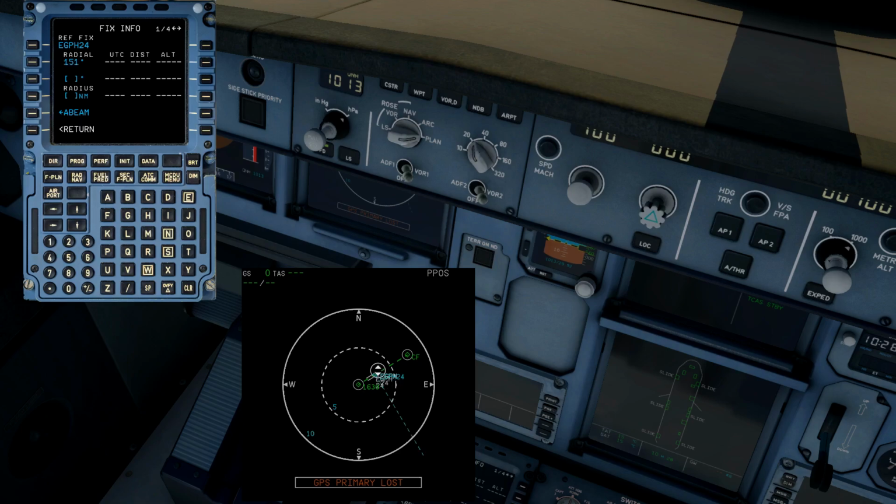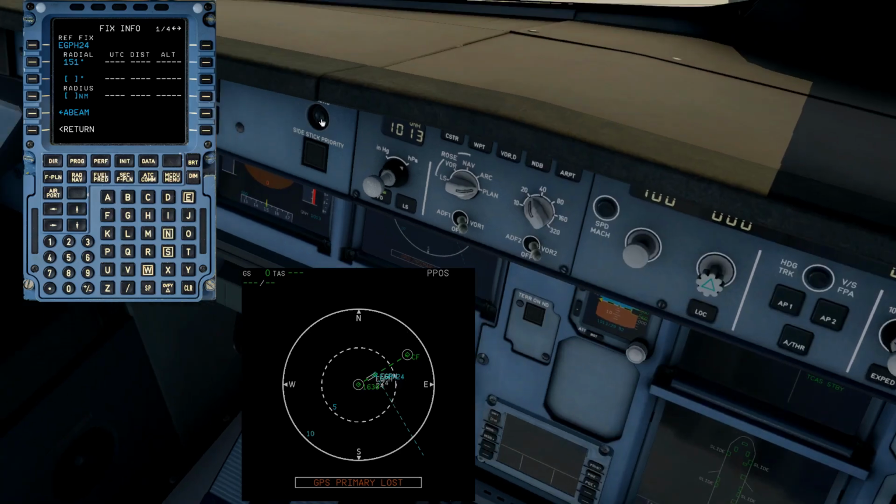So we can see that there is a beam which is blue in color, perpendicular to the threshold. So as soon as we do a 25 degrees of bank left hand turn here, and we are crossing against the runway, as soon as we pass the beam of the threshold, we'll start the clock. This is known as a chrono. As soon as we reach 35 seconds, we start a left turn back to the same runway. So that's the flight plan.